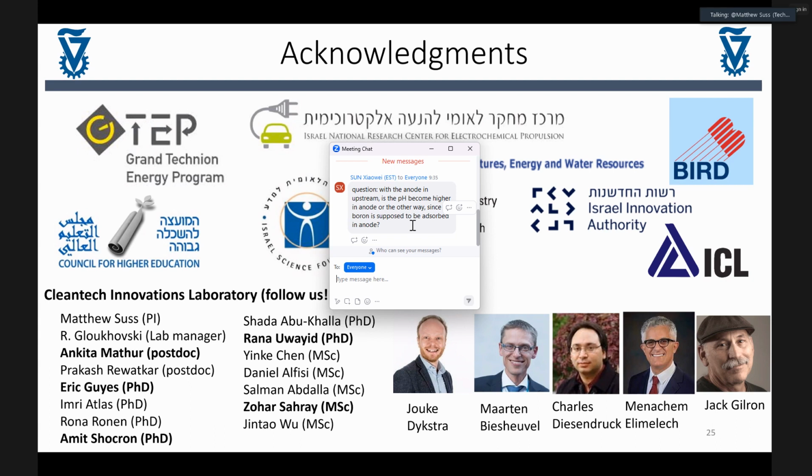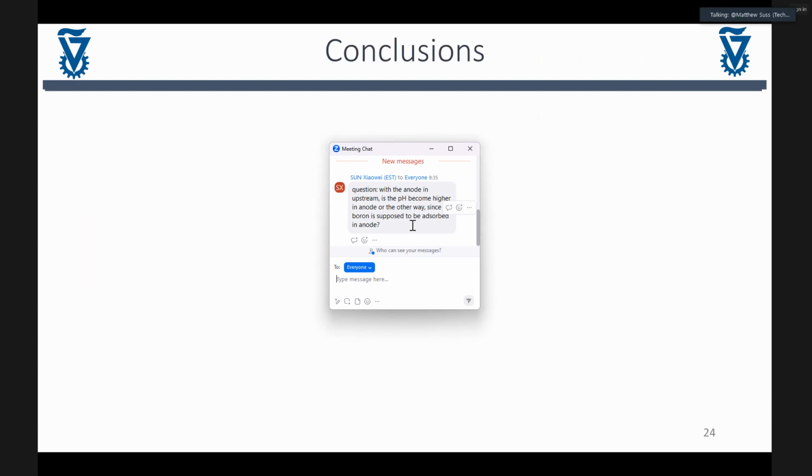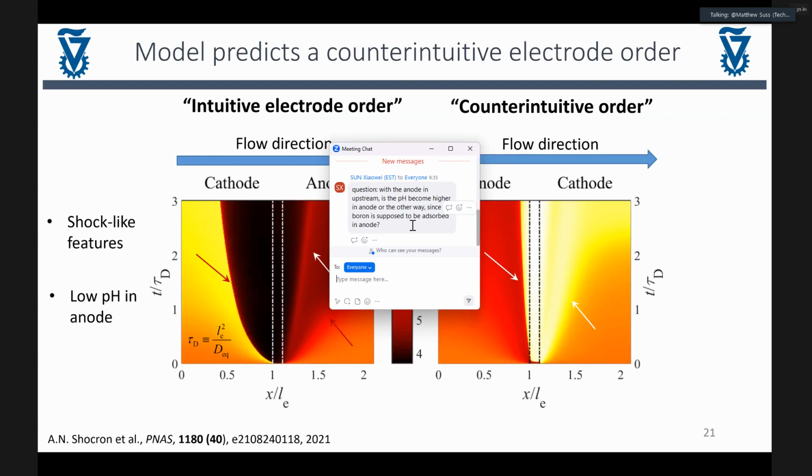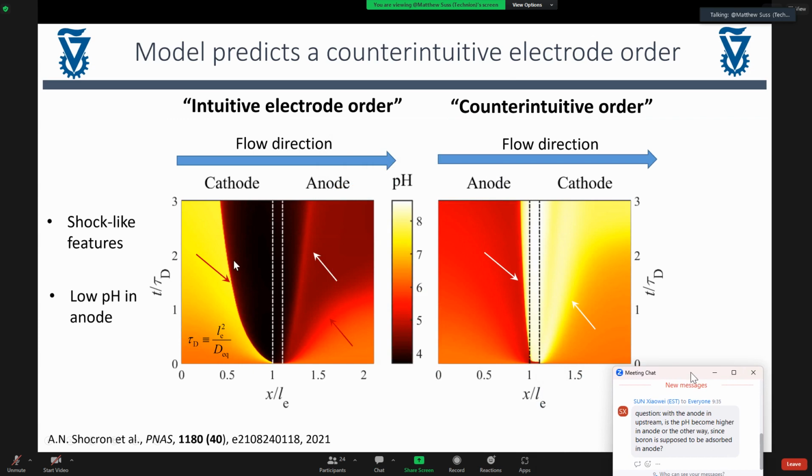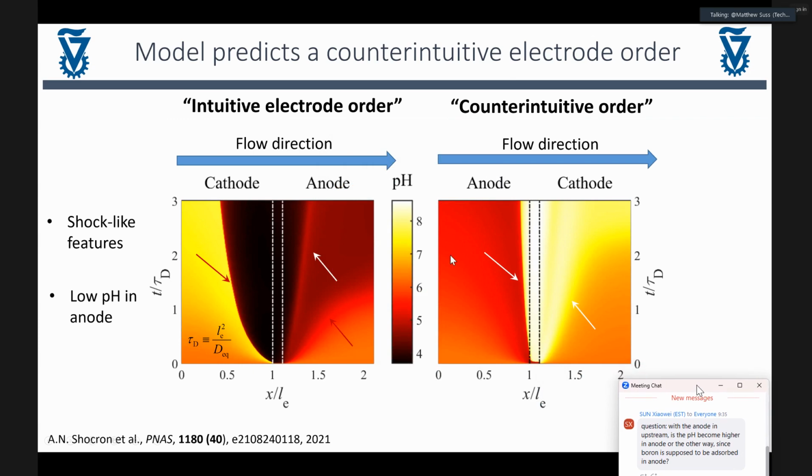Yeah, okay, so when the anode is upstream, I'll just quickly get back to those results here. We have these predictions. We, of course, didn't measure pH inside the electrode space. I wish we could do that, but we don't know how to. So the best thing we have to understand the pH is the model predictions. What they predict is that for most of the anode space, where the anode goes from 0 to 1 on this x-axis, the pH is below that of the feed. It gets acidic. But there's this small band right here where the pH goes up.